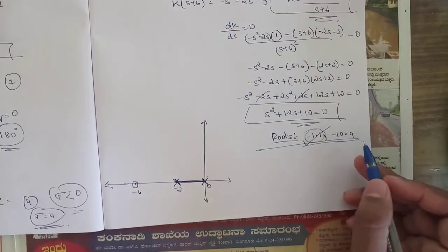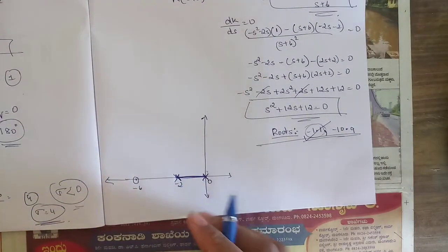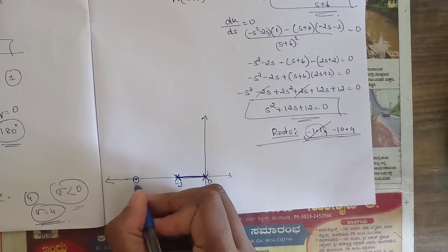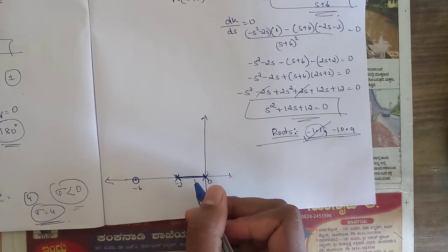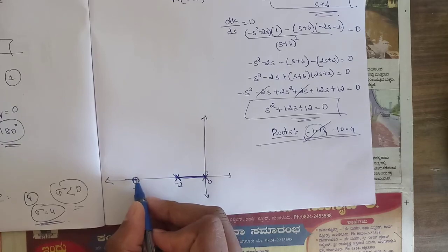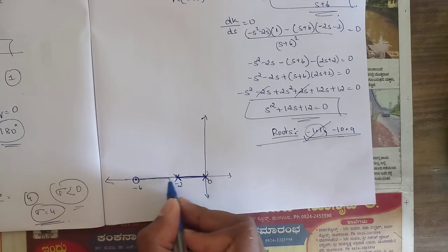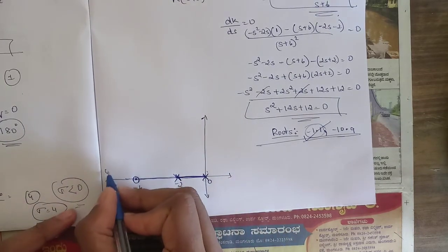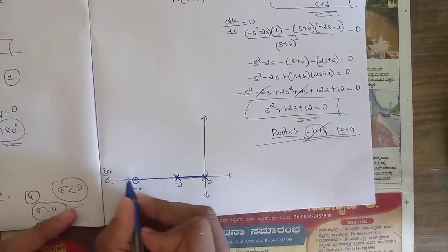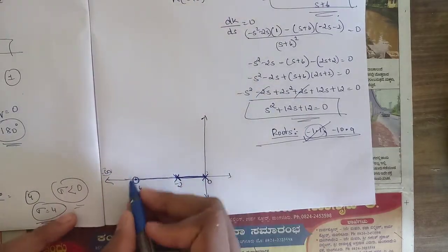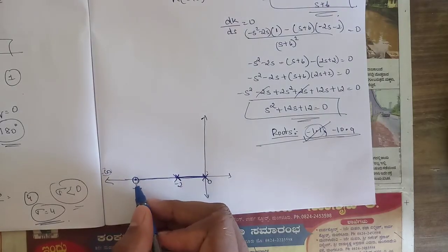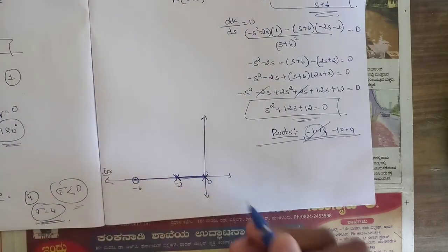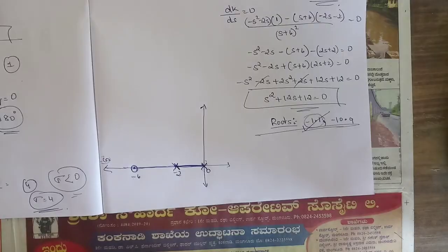Also for minus 10.9, if you look from 0 towards the right, we have two poles, that is an even number of poles, so that region is not part of the root locus. But from minus infinity, if we look towards the right, we have three quantities, adding the zero as well, one zero and two poles.